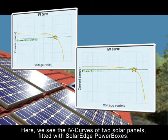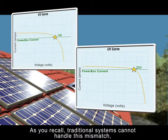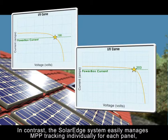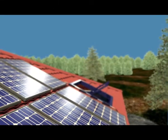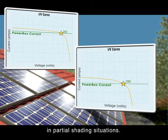Here we see the IV curves of 2 solar panels fitted with SolarEdge power boxes. You can see that the MPP point is different for each panel. As you recall, traditional systems cannot handle this mismatch and will adjust to an average point, resulting in power losses. In contrast, the SolarEdge system easily manages MPP tracking individually for each panel, harvesting the optimal available power. This same capability also ensures the SolarEdge system will harvest more power in partial shading situations.